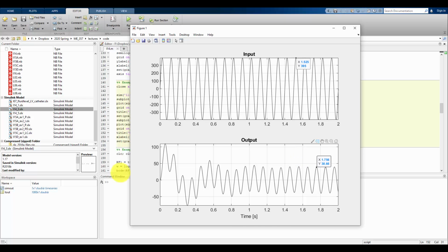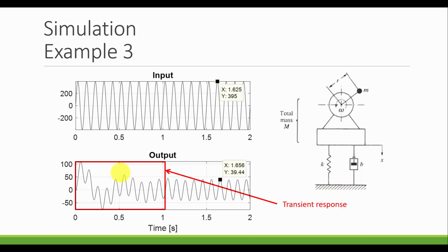So as a quick recap of what we did here, we used the relative frequency Bode diagram because we did not know in this design step up front what the natural frequency was. So we couldn't just put in the Bode diagram. We didn't have enough information yet. So by setting that natural frequency to 1, we were able to make a relative frequency Bode diagram and at least see what's the relationship between the input frequency and the natural frequency. From there, since we had the desired transmissibility of 10%, then we were able to select what the natural frequency had to be in order to get that 10%. Now that we knew the natural frequency, we could get the K, we could get the B from our transfer function. So on paper, it looked like we did what we were supposed to.